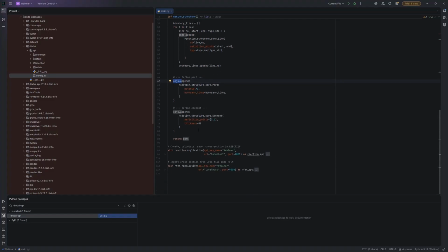Additionally, an element is defined between the middle points. This means between the points 5 and 6. This element is assigned the thickness dt. An element object is then created in the Rsection API and added to this object list. The object list now contains all objects necessary for the cross-section.